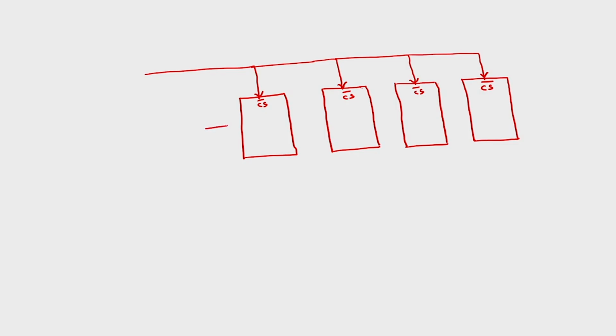They have the same number of address lines, 5 address lines, A4 to A0. You connect these to A4 to A0 of all the remaining memories, together.